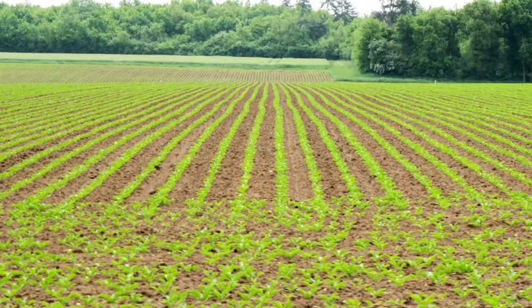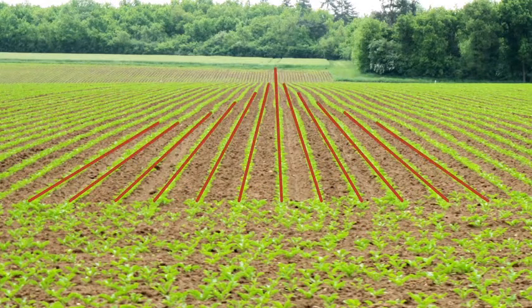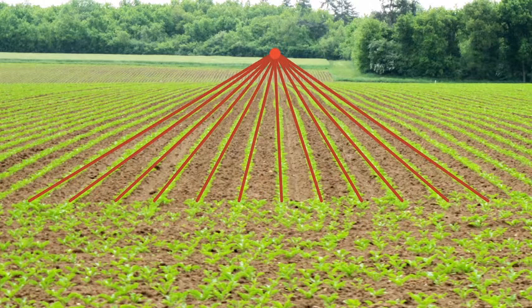Probably the most important concept we need to know about sketching in perspective is understanding how we see parallel lines. Lines that are in reality parallel to each other, like the rows of crops in a field, appear to converge to one point off in the distance as those lines recede away from us. That one point off in the distance is called a vanishing point.